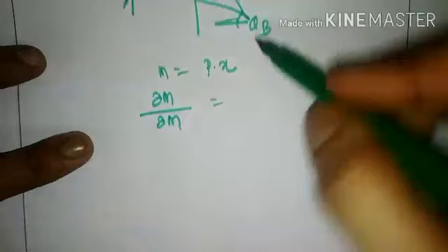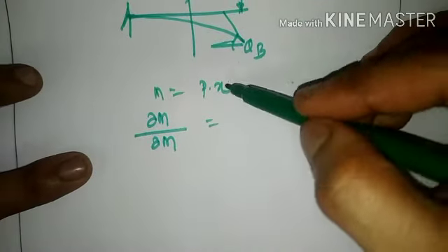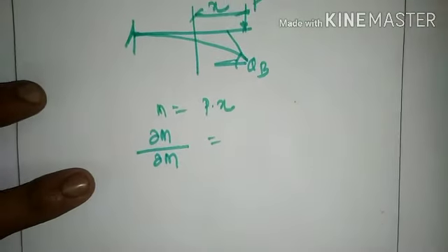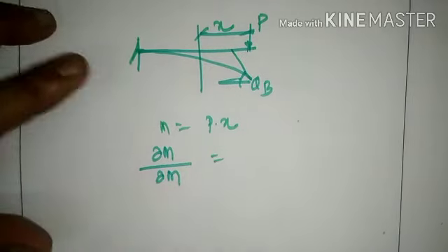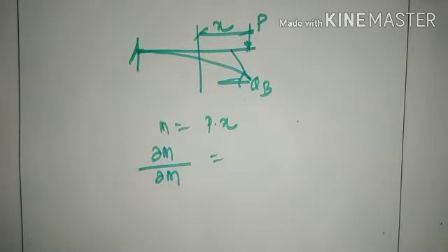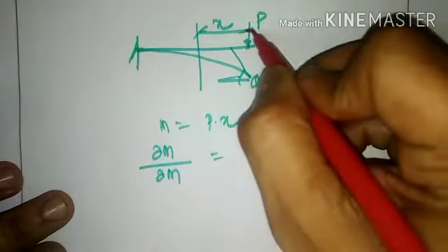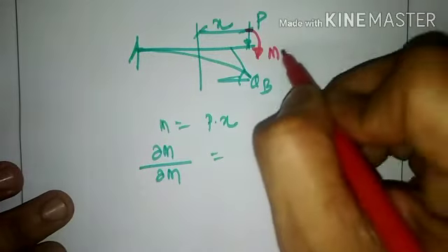Now if I consider this equation as it is, I will yield this particular term as 0 because I don't have a moment. That is the reason why I had instructed you before to impose a rotation force if we don't have one, and that rotation force is called a dummy moment.